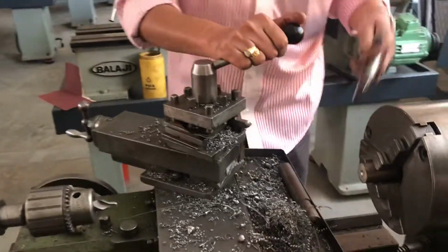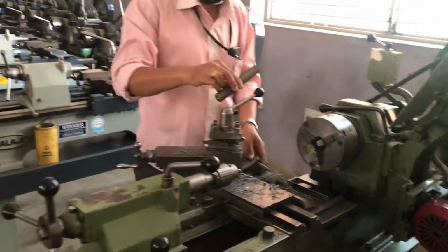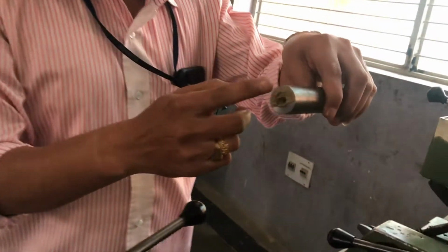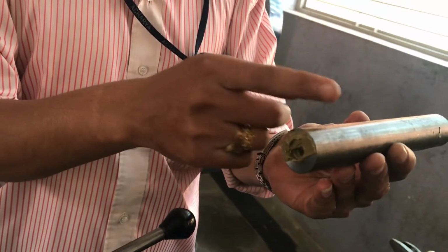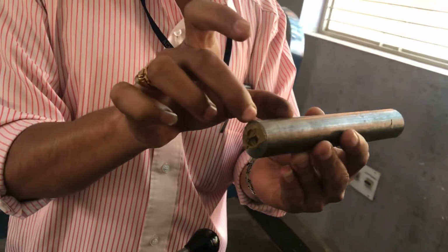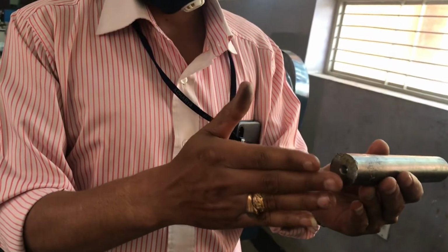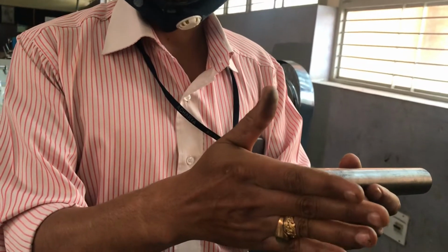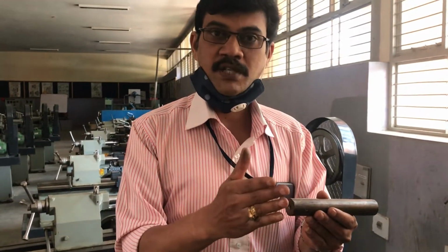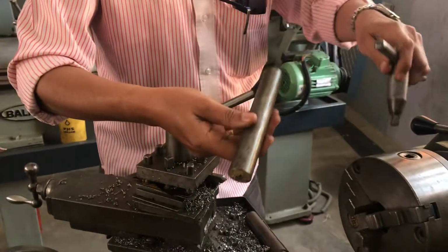So actually, what you want to do for facing operation is this: this side is already a flat surface. So from this side, if you go for marking, from here to here you will get, for example, 30 mm all around the circle, exactly 30 mm. But on this side there will be unevenness. When you do the facing operation, you will reduce the length, and you will also get an exact surface level. For marking purpose also, you should do the facing operation. So now, next operation will be facing.